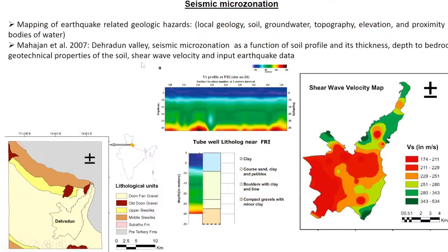We can conduct seismic microzonation with the help of PGA analysis, meaning the seismic data, and multichannel analysis of surface waves, and we can give information about how much amplification there would be, and how much damage will be more. All this we can give more information about with the help of this MASW data.